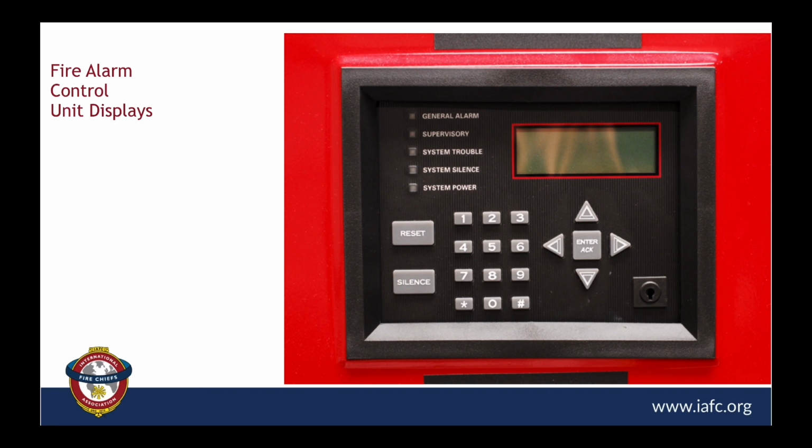Now, it's smart enough to know that when you hit the reset and for some reason a pull station has not been completely reset yet, or there's smoke in a detection chamber, or there's a water flow switch that's still flowing water, when the system recycles, it will go back into alarm again if it sees one of those initiating devices still in alarm. So those are the important key buttons and lights that you're going to find on almost every panel that we're going to view here. So let's go down to the next slide, Chief.